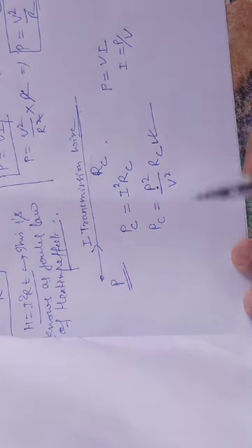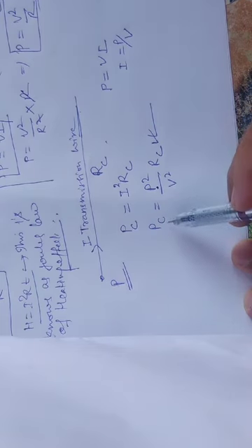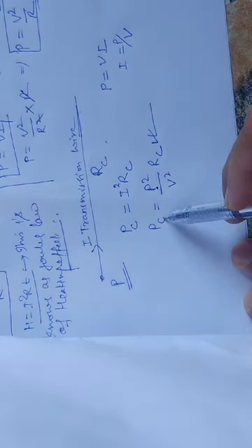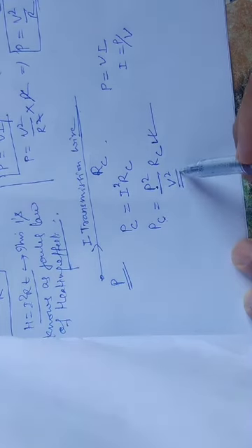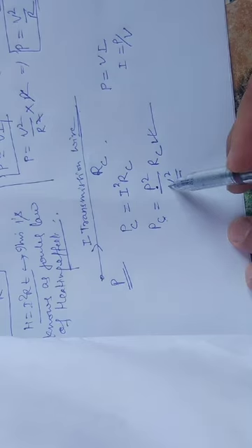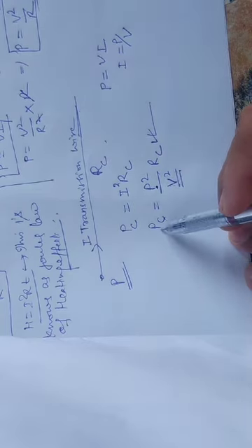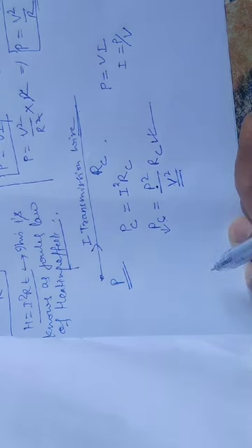From here you can see that the amount of electrical energy which goes waste varies inversely with the square of the potential difference across the ends of the wire at which it is transmitted. Meaning if higher is the value of V, the lower is the loss of energy.